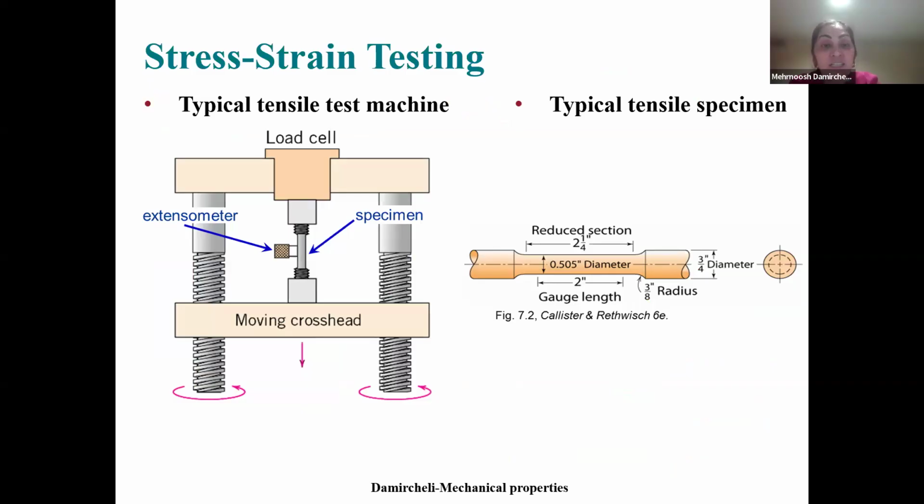Okay, the stress-strain test is a very important test for measuring many mechanical properties. Today we want to talk about that. The stress-strain test measures how a material deforms under load. It provides key properties such as Young's modulus, yield point, yield strength, yield strain, tensile strength, toughness, resilience, fracture behavior, plastic region, and elastic region. We can derive a lot of information by doing this test.